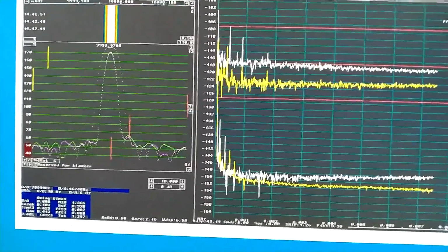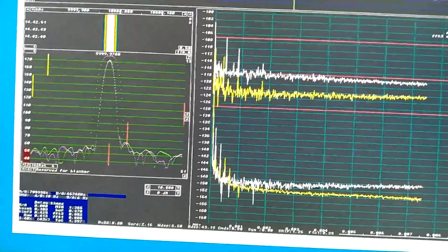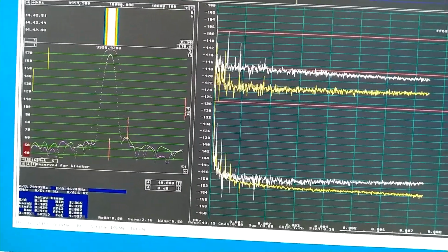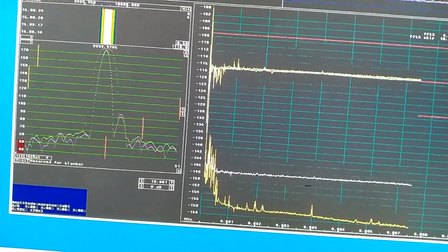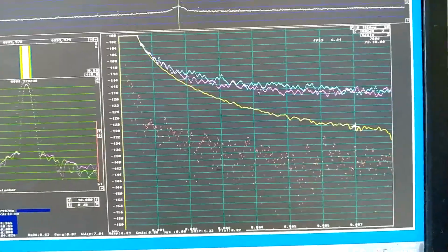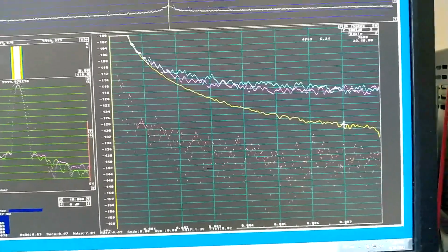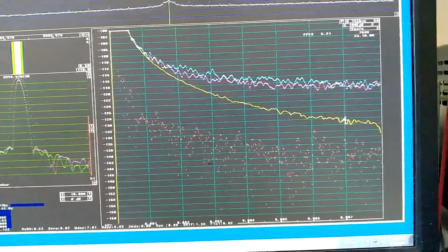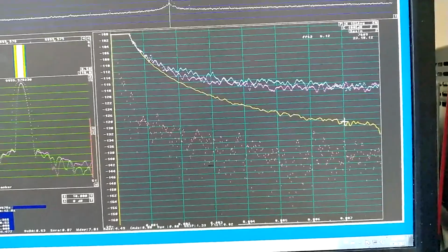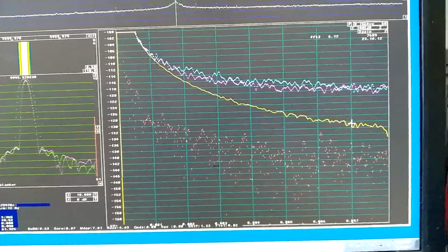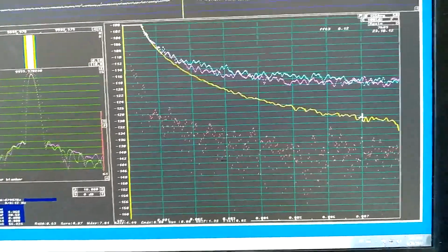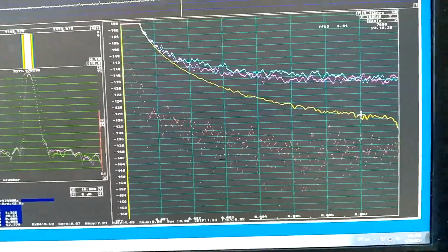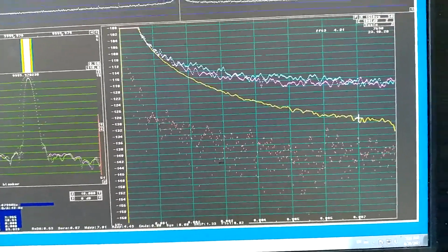This is without the limiter. So the phase noise at 10-20 Hz or so has become much better. The amplitude limiter no longer degrades the close-range phase noise. It's the same as I had when running without the limiter directly on the card once the capacitor was removed.